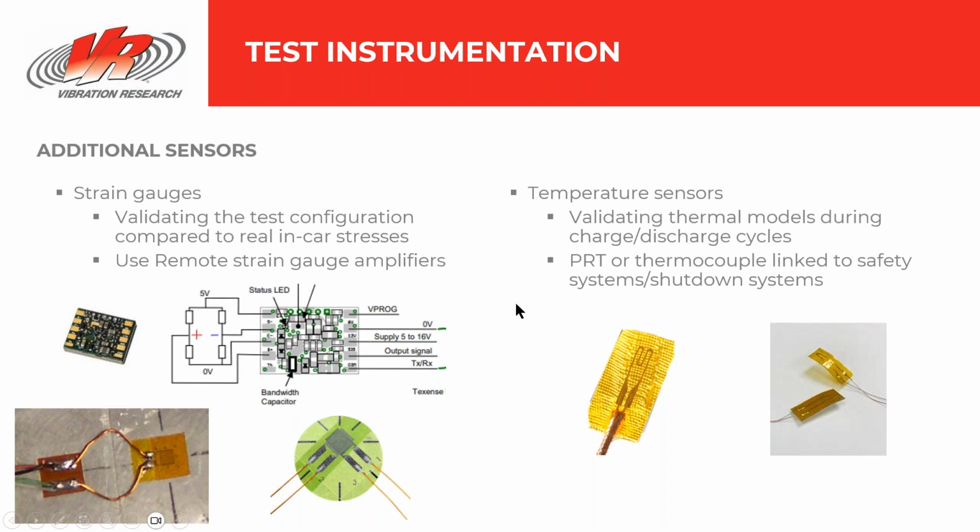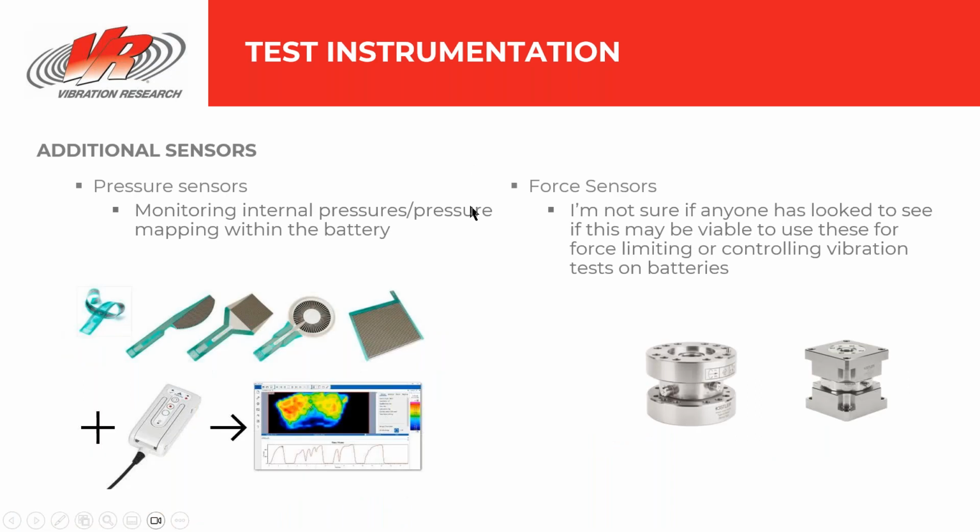So on the 9500 and 10500 controllers, you've got those inputs available on the back of the controllers that log at 1 hertz. So you can take these temperature measurements and actually use them and report them in your reports, as well as use them as safety trips.